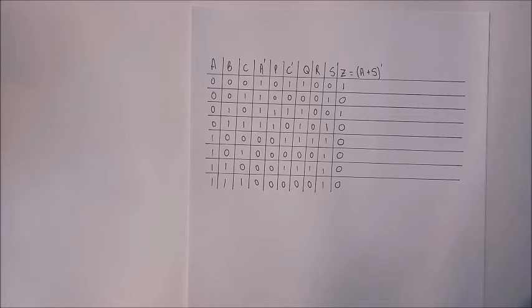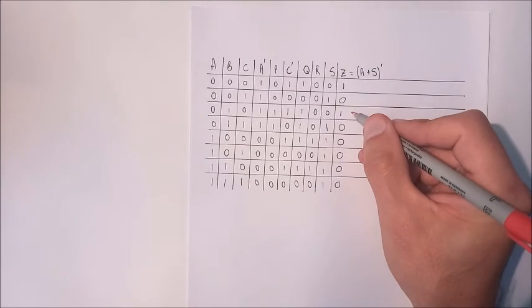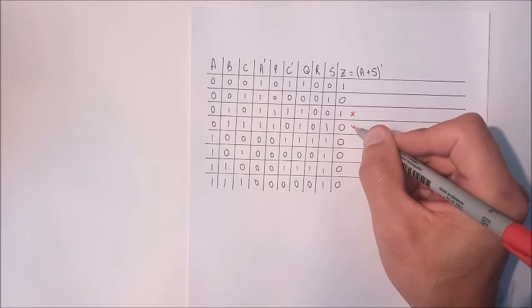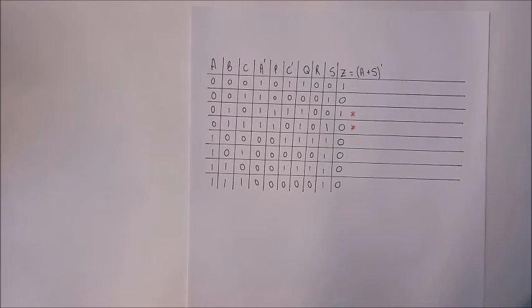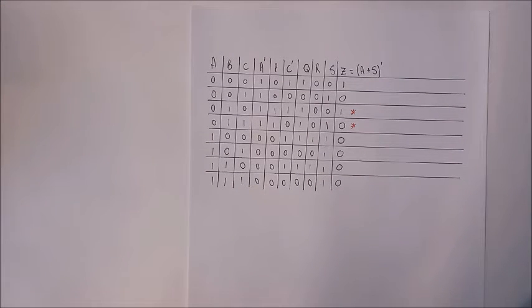So just be very careful with these types of truth tables. As you can see, when one does rush it, it is possible to make an error. Look at specifically those two lines, how easily I made an error unintentionally initially. But I thought to leave that error over there so that you can see how easily it happens. One just needs to be really careful when you do these truth tables. Okay, so let's have a look at another example.